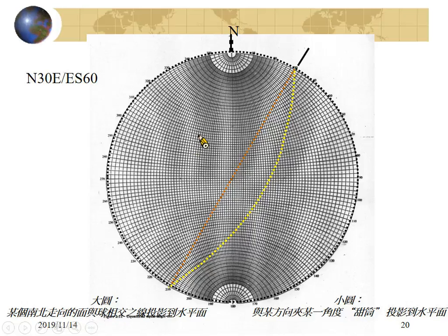Do you know where the dip direction of this plane is? Where is the dip direction? Do you still remember dip direction? You have a plane. You have infinite numbers of vectors. But only one vector has the largest dip angle. The largest plunge, sorry. And this direction will be the dip direction. So where is the dip direction of this plane? It will be here.